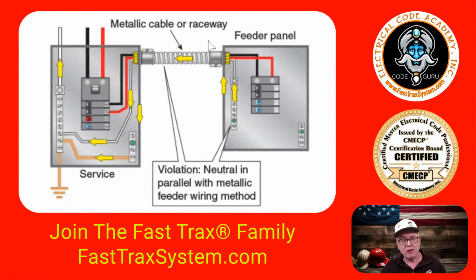Well, yes, 250.118 does give you a list of things that are allowed to be used as an equipment ground. But because the conductors in here are probably larger than 20 amp protection, meaning the overcurrent device is larger than 20, because it looks like this is a feeder panel downstream, let's say probably 100 amp rated, in that case you're not going to be using liquid tight flexible conduit. You're not going to use flexible metal conduit because they have limitations on the amps, and that would be a problem. So that's not going to be used.